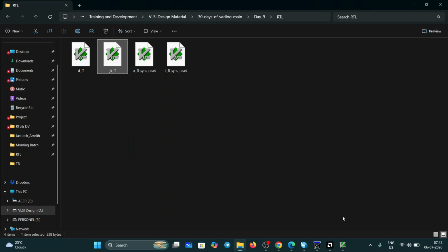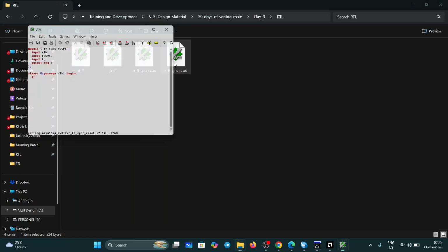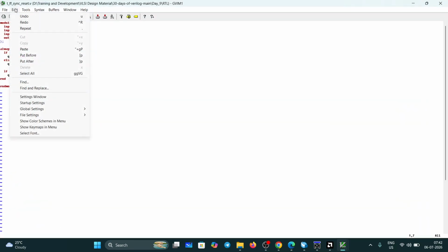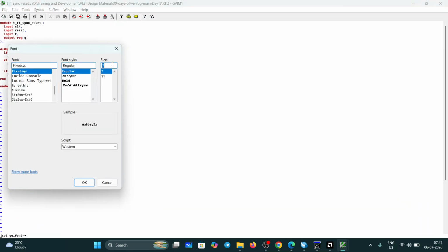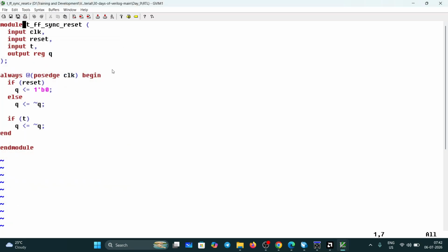And next, as I told you, from SR flip-flop we will get the D flip-flop when S and R are connected with an inverter. From JK flip-flop, we'll get the T flip-flop, when J and K are connected together. Okay. So when J and K are connected together, that is a toggle flip-flop. So only two states will be there. When J equal to 0, K equal to 0, that is the present state. J equal to 1, K equal to 1, that is toggle state. Okay. So from JK flip-flop only, you'll get the T flip-flop.